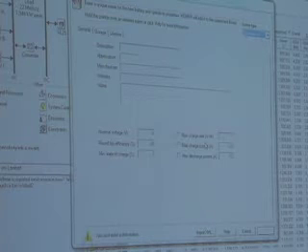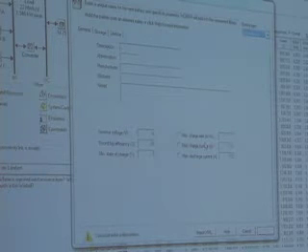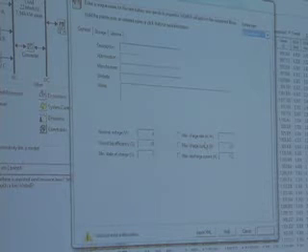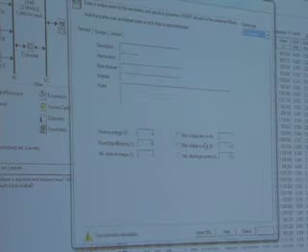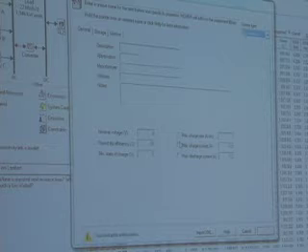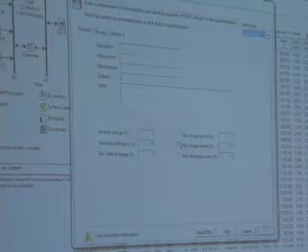That's a way to, when you're charging a lead acid battery, you have to approach 100% state of charge sort of asymptotically. You have to slow down the charge rate as you near the top, and it gets less efficient at that point. So that parameter is in there because of the behavior of lead acid batteries. So for the ZBB, we don't have that.